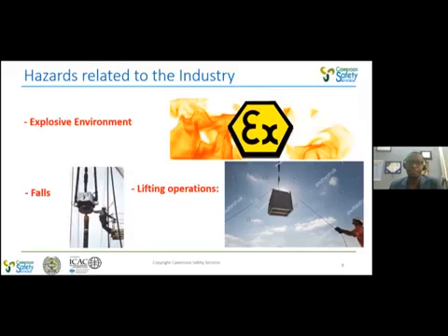We equally have hazards like falls. People have to walk at height, either during equipment maintenance or the guy who is working at the mast trying to connect pipes. If he does not know how to use the PPE that has been given to him or her, like a safety harness, he runs a risk of falling. There are stairways you have to move overhead, and maintenance on the crane. These are activities that require people to walk at height, so it can lead to falls. Even in living quarters where the crew live, there are possibilities of falling down the stairs if people descend and climb stairs without proper techniques such as using handrails, so they can trip down. So either on the same level or at a different level below.